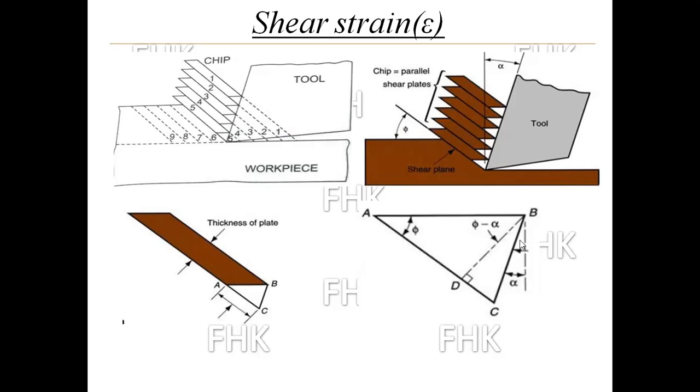This angle will be alpha, and we have to find the unknown angle included between them. The total angle between AB and the vertical line, together with the rake angle, is 90 degrees. So 90 minus phi plus the unknown angle plus alpha is equal to 90 degrees. The 90 gets cancelled, and the unknown angle is phi minus alpha when phi and alpha are moved to the right side.